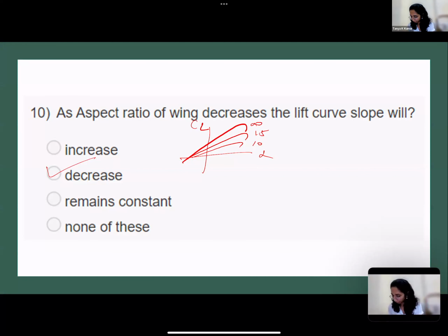So if this is the wing, the airflow at the bottom and the top interact at the wing tips. And here you have some vortices generated which travel downstream. But what happens here is that the amount of lift that the airfoil could have generated is not generated for a wing because of this vortex generation. Okay.